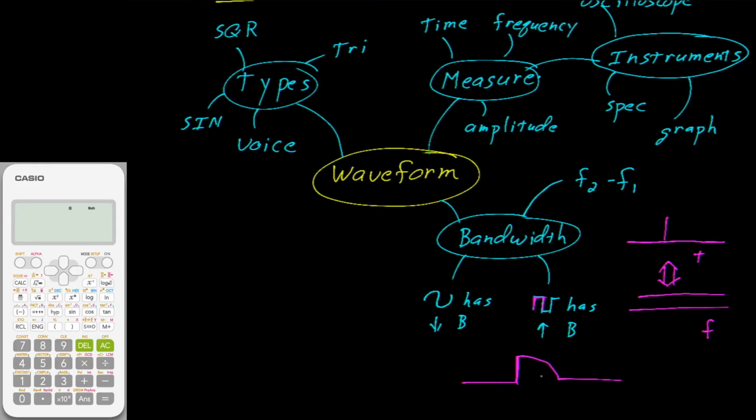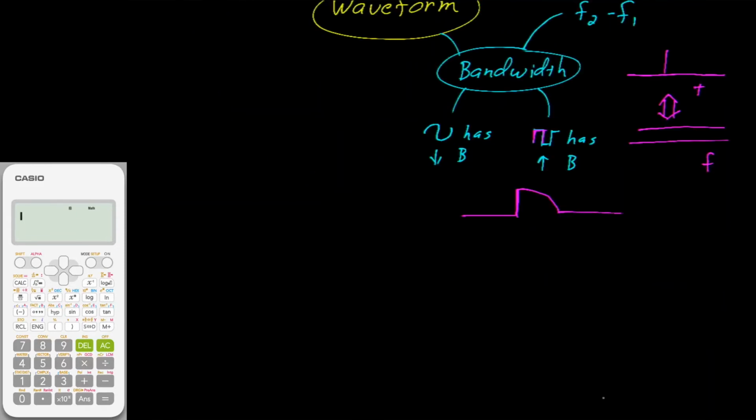Now, it's not exactly a square wave, but you can already do some guesstimation here, and you can talk about the fundamental frequency, and you know darn well that there's going to be harmonics out here. Some of those may be odd, some of those may be even, but they're going to be there. So what would appear to be, say, a 60 hertz waveform will have harmonics that extend way up, sometimes even into the radio frequency range.